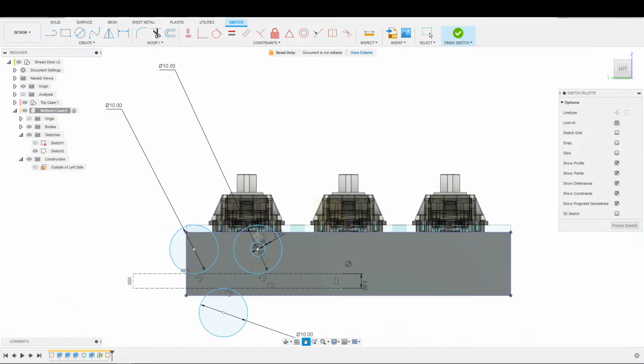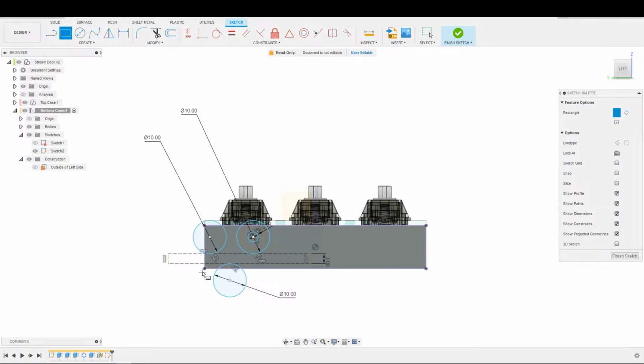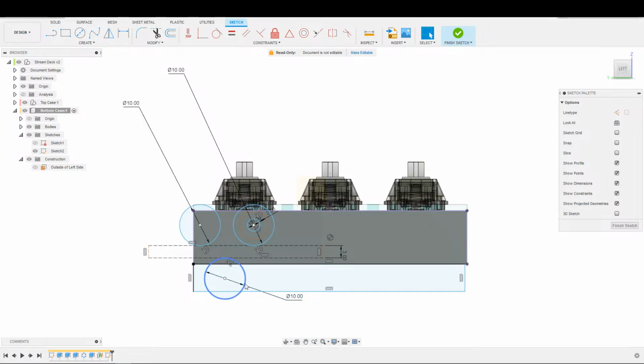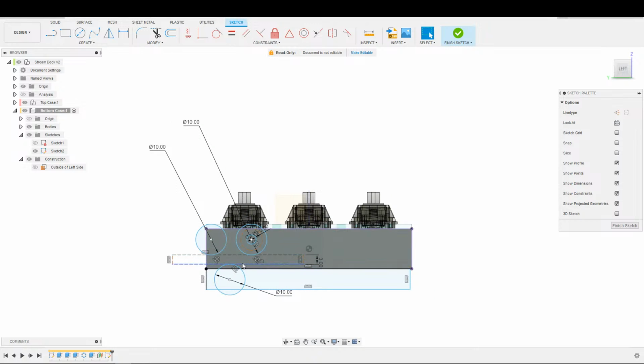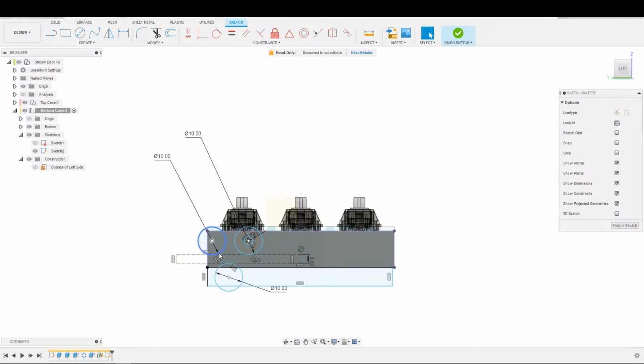So in theory, imagine the case being this much larger-ish. Technically speaking, I still need to figure out this bottom guy. The rail goes on here, and the rail does not pivot because it has 3 points of contact with these rollers. So even as we slide the rail out this way, there we go. So long as it is still in contact with this front roller, it can't actually pivot up and fall off. So this is a way we can design this with these 3 rollers at the back here. However, I do need to make this case bigger.